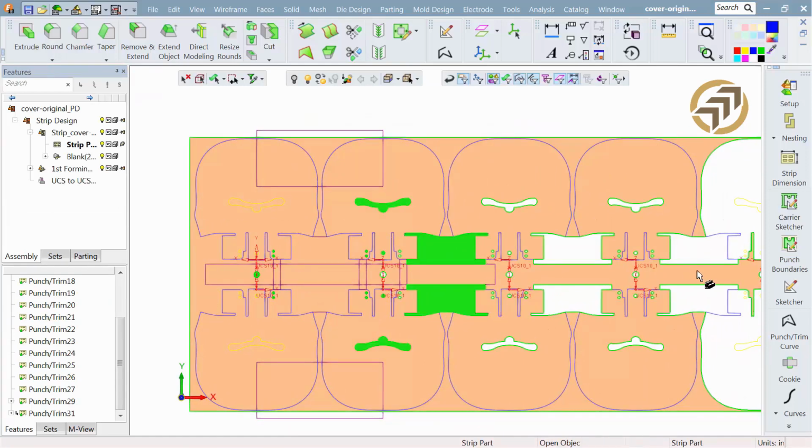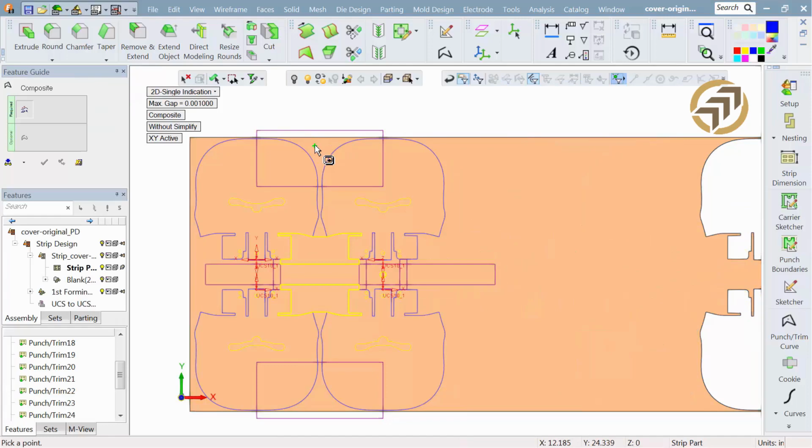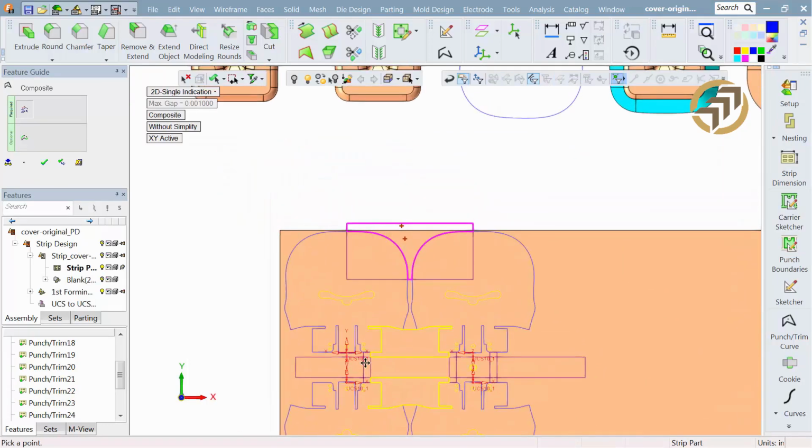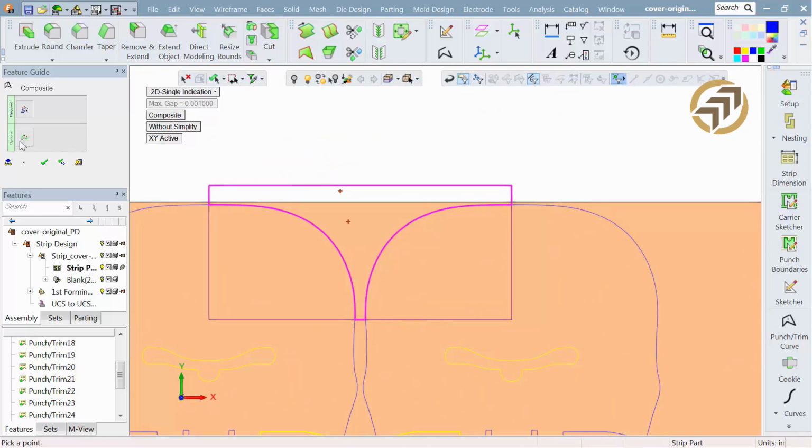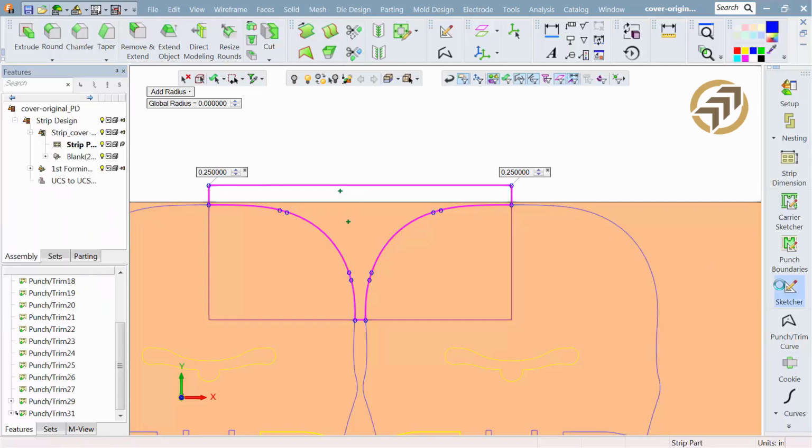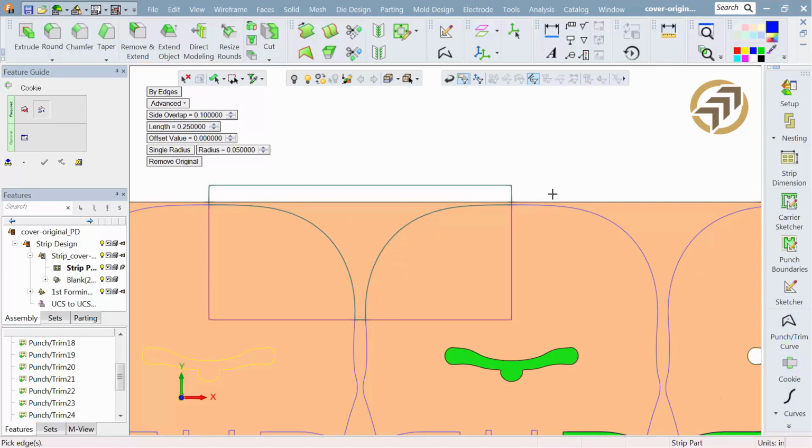Right. Now with these wire EDM punches, those green faces I'm going to use to actually create the 3D geometry of the punch. If you notice as I pick, I'm picking inside an area and establishes the perimeter, and then I pick outside of it, even though there's no face underneath it because this is going to go into the material guide area, it still allows me to pick that perimeter. So it's a very intuitive tool.